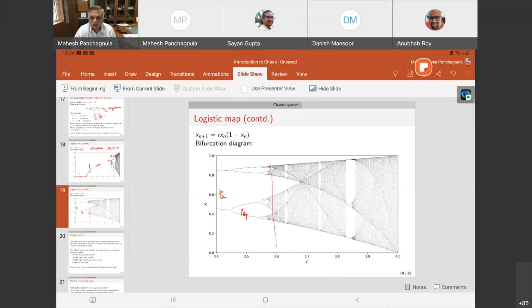If you compute the Lyapunov exponent and it is positive, then it is very difficult to calculate error propagation. At least for sure the error propagation would be exponential after that. Below that, of course, you can estimate what the error propagation is. So in fact, there is a whole school of literature that argues that turbulence is nothing but a period doubling route to chaos.